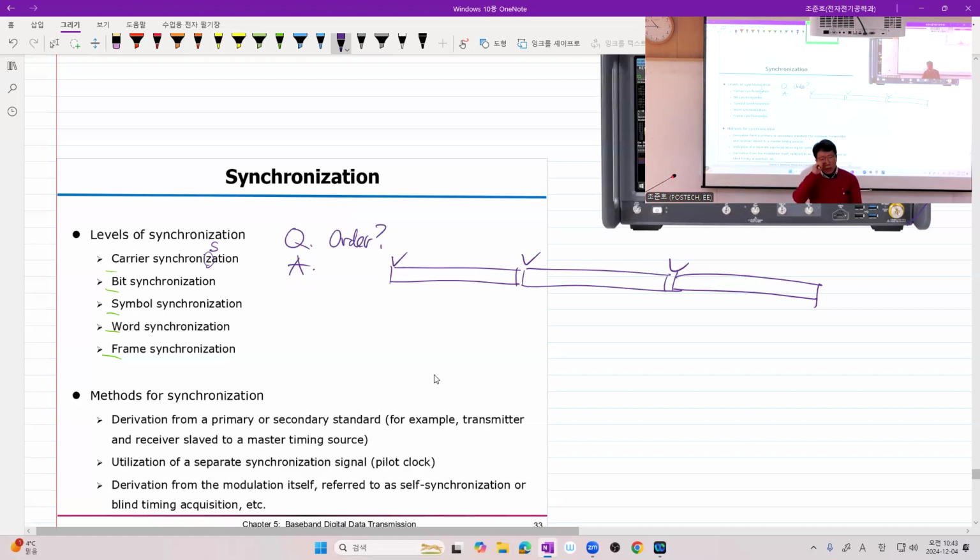For example, in direct sequence spread spectrum, which is usually designed to have low probability of intercept by enemy or unwanted receivers, the signal is very weak. In that case, if you try to directly recover the carrier frequency or phase, your whole synchronization procedure fails.